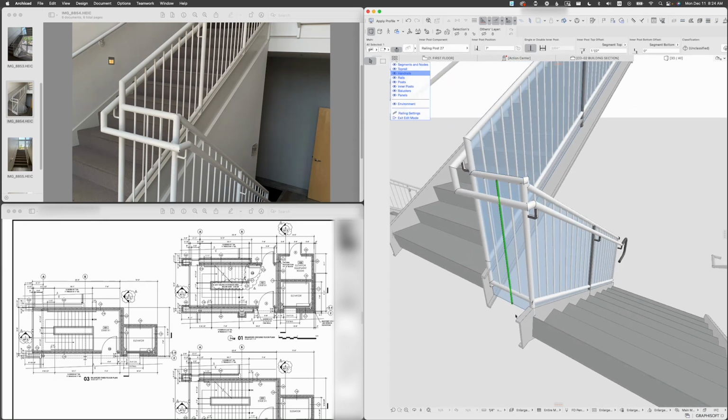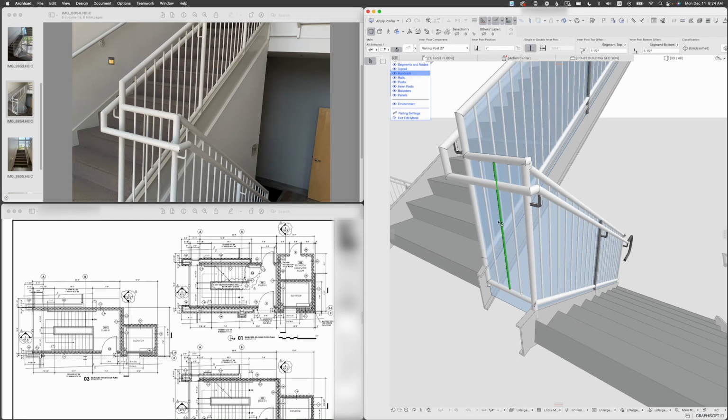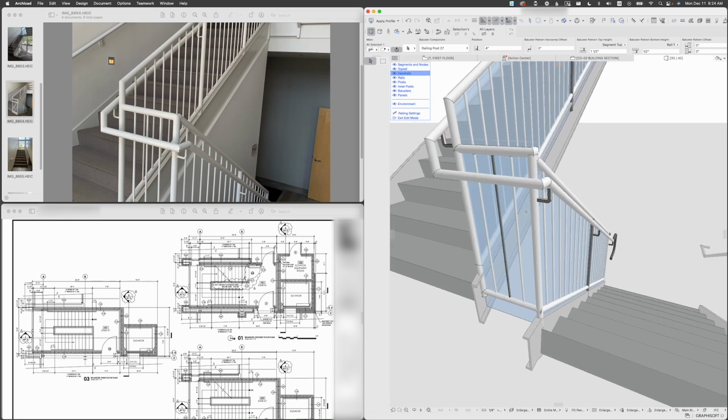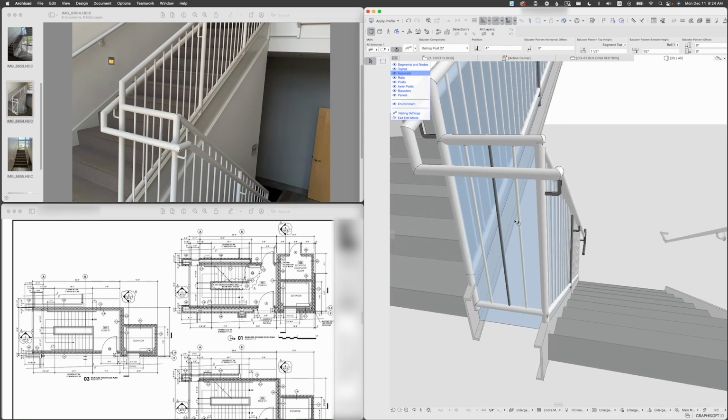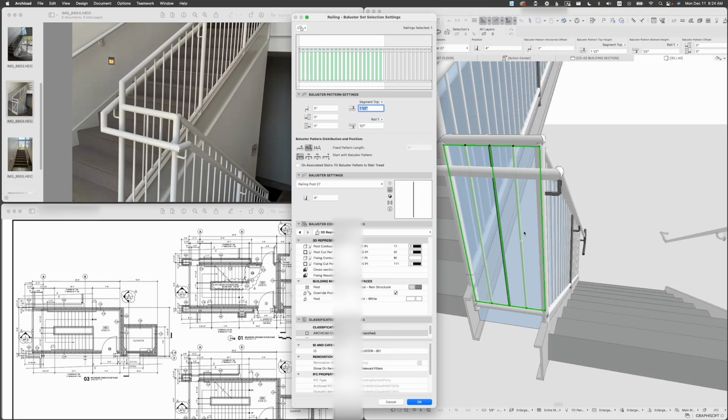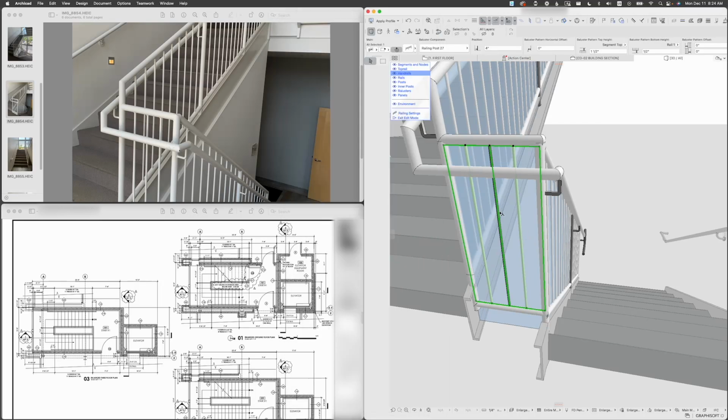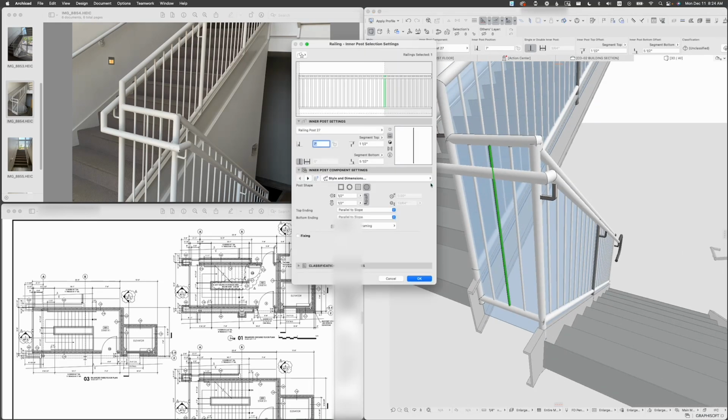Now the only thing is I have to move it up, so I could click here. Let's see if I can. Yeah, it allows me to move it up. So even though I know that this is not what this element is, because this I can't even select, I must adjust the entire segment, and those are called balusters. But at the same time, I just set up the inner post to look exactly the same as the baluster components. So that's why we don't see visually any difference.